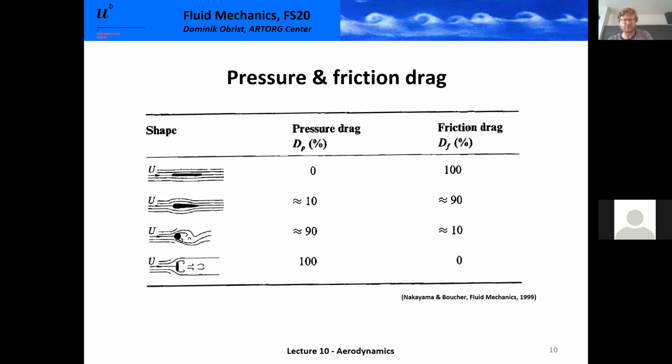Okay, so the only drag that we see in this flat plate is due to pressure drag. It's due to this huge difference between the pressures on the upstream side, which are high because we have a stagnation point on the upstream side, and the pressures on the downstream side, which are relatively low because we have a huge wake and the flow is certainly not coming to zero velocity. And then, of course, we have everything in between.